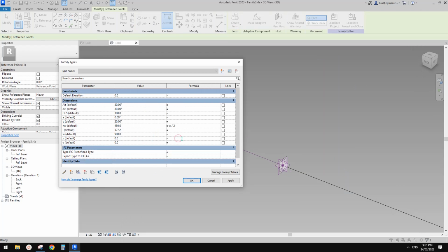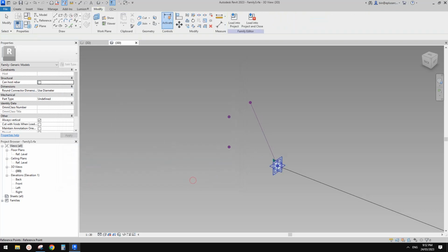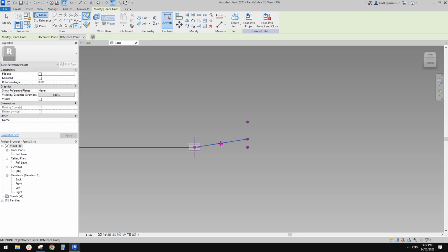X here, so tangent, TAN bracket ALT altitude times time of OFS. Okay, the same. I'm going to copy this, Control V, just change altitude to azimuth. Okay, offset, apply. Okay, so now this should be it. And then we just need to place a point. You draw on face, place onto this reference line.